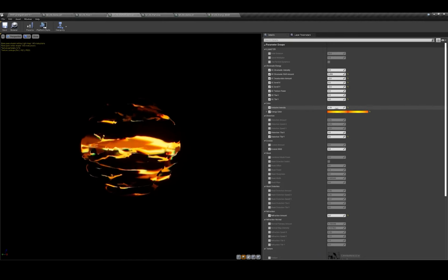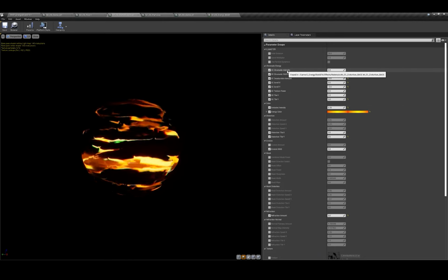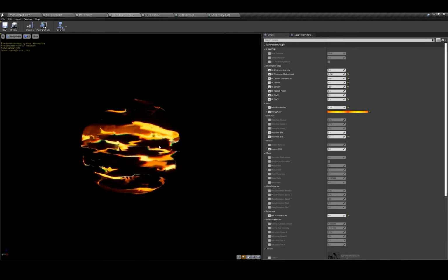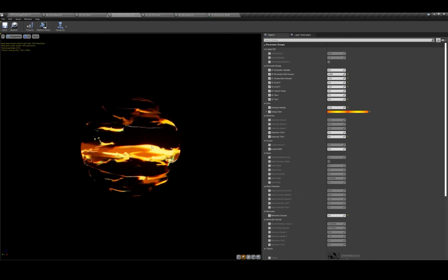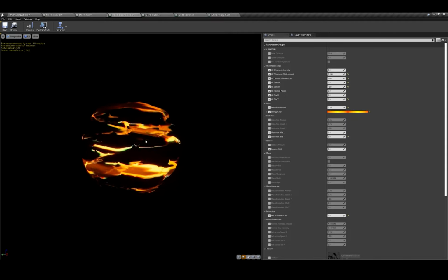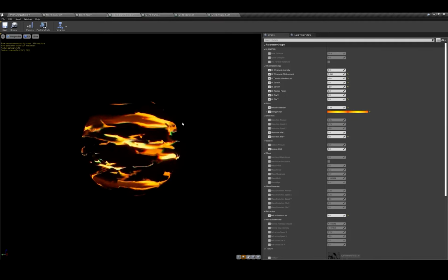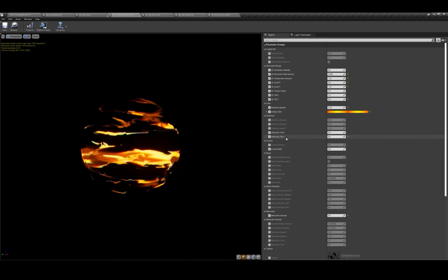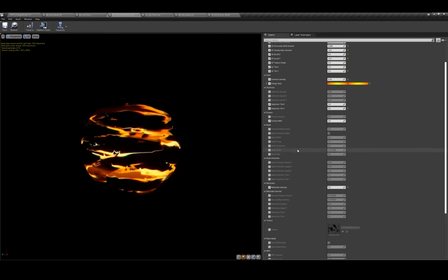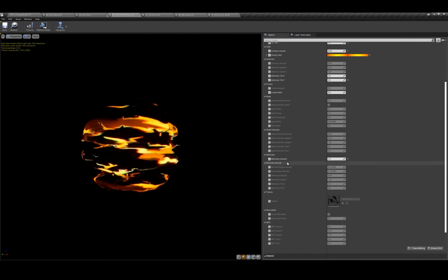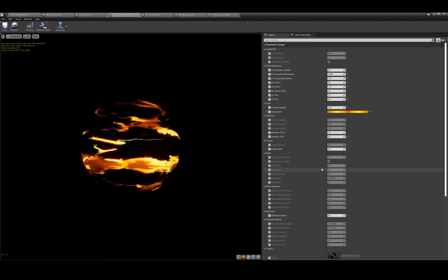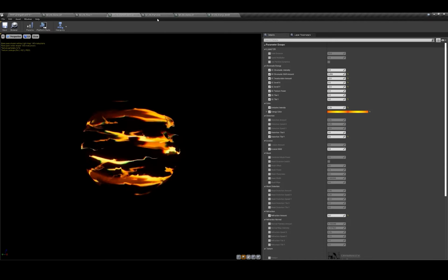So I kind of lessened that a little bit and changed some of our chromatic energy settings just so that the blending of that RGB shift with this orange wouldn't compete. I just wanted a very, very subtle kind of chromatic shift there. You can see some of the other settings I changed in the distortion and the erosion, as well as the refraction amount. And that is basically it for our material instance for the dome distortion.